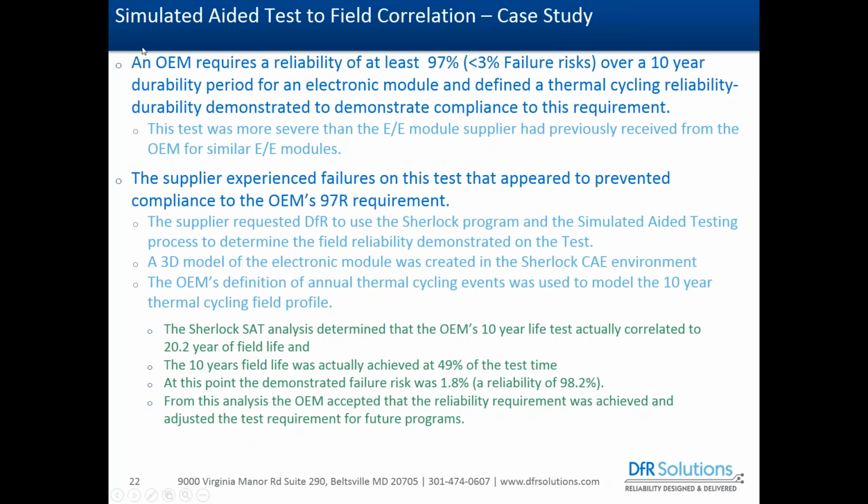So a case study of this that we did here not too long ago: an OEM required a reliability of at least 97%, or less than a 3% failure risk, over a 10-year durability period for an electronic module. And they defined what they believe to be a thermal cycling reliability durability demonstration test that would reflect this 10-year life cycle.